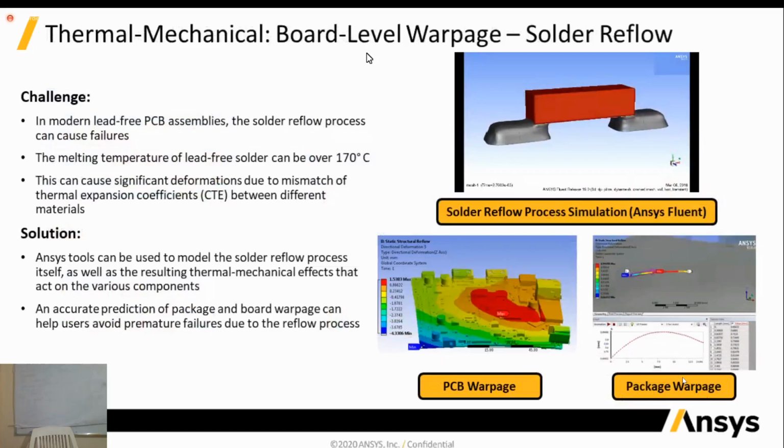This is an example of a solder reflow analysis. The video here is done using Fluent on the reflow process, because this reflow process happens at a high temperature, and this can lead to a lot of deformation due to thermomechanical effects. Basically, it's due to the CTE, coefficient of thermal expansion.